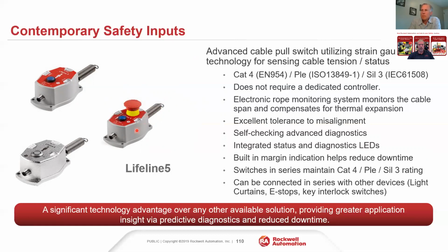What that allows us to do is develop a fully solid state, highly diagnostic capable product that provides us great information and increased performance, because this thing is set up so that a light push against that cable, if you just happen to brush by it as you're walking by, it doesn't care. It only is going to trip when it sees the tension go outside of the applicable tension window, or when the speed of pull is beyond a certain speed that it is looking for to understand that someone is trying to pull that cable to stop the equipment, as opposed to something just leaning against the cable.